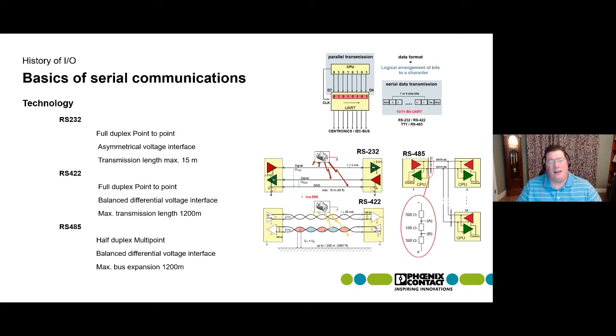So they're looking at, okay, well, let's look at these individual serial technologies and figure out which one will work for us. Now, they're all great. They all work. They all have their advantages and disadvantages depending on environment. You've got 232, which is a point-to-point network. You have RS-485, which is a point-to-multipoint network. And then 422 is another point-to-point network style. These are all just communications concepts or physical mediums that were used.